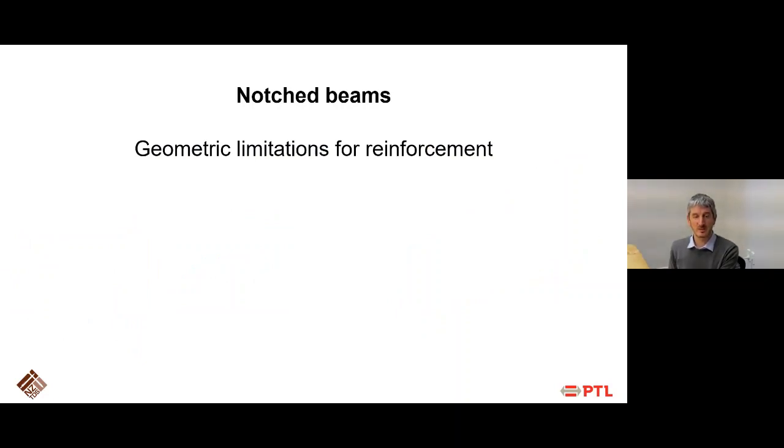There's obviously limitations of when you can reinforce. So there's a maximum distance or maximum depth as well. But there's also indications of how close or how far away reinforcement needs to be installed. Obviously, the closer to the singularity, the closer to the notch, the better.